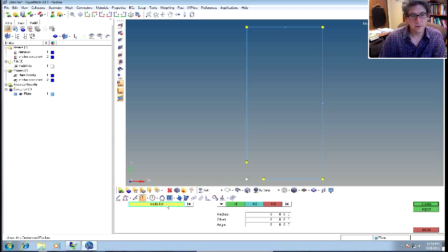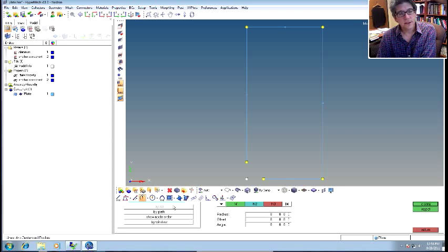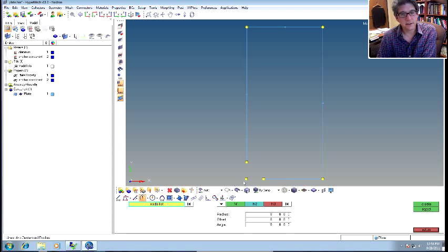That's this one. Yeah, I should talk about this a little bit. This is kind of weird. This always pops up in Hypermesh. You can kind of have different select options here, and then this button actually clears the list. You can see, actually, if I pick the center point, there it goes. And so that node list, highlight that, and then click the center point.